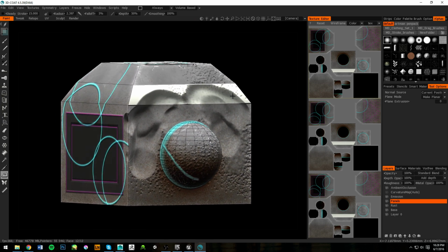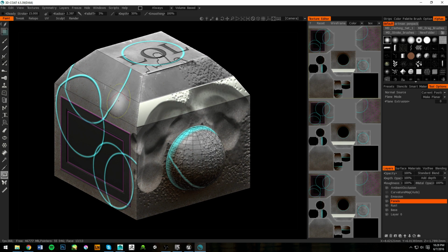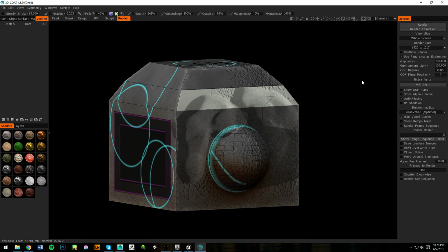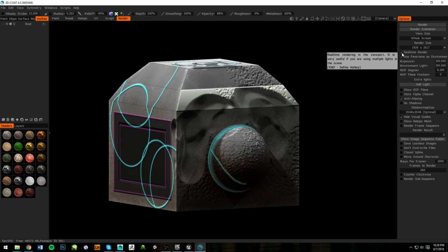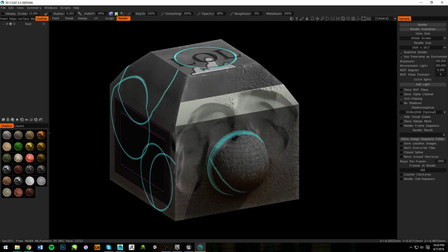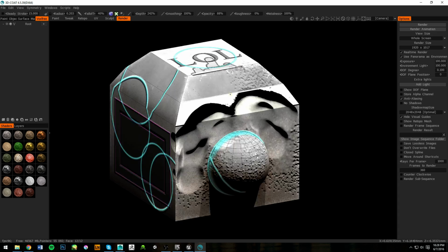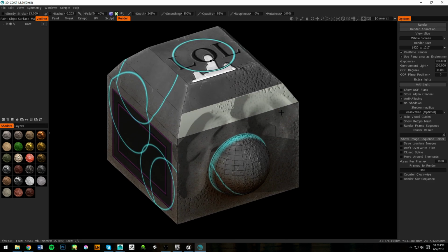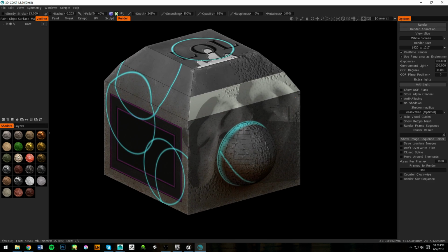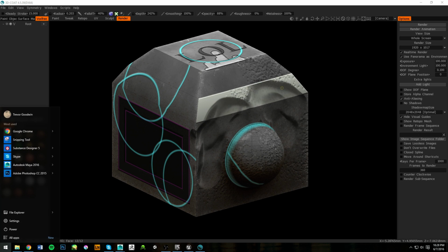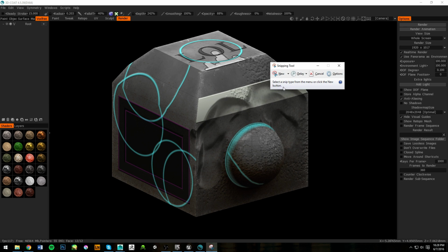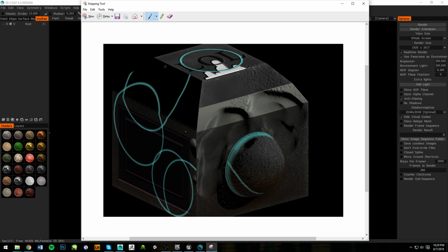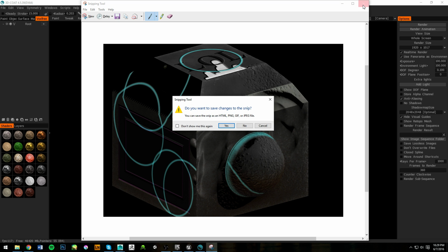I'm going to go over the render room really quickly because it's a good way of sharing your assets with a group. All you have to do is click render, and it'll be rendered in this room. You want to click real-time render, and it'll render by itself. You probably want to turn wireframe on for this so we can look at the topology of whatever you're making. Then all you have to do is open the snipping tool, click new, make a selection of the object, copy it, and paste that directly into Slack, which is really nice.